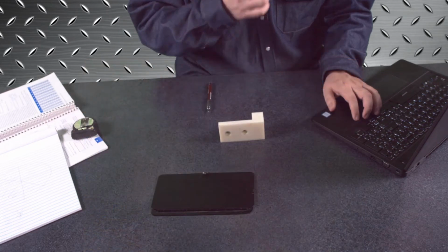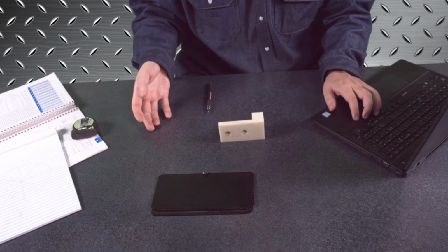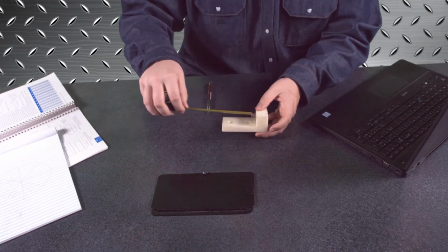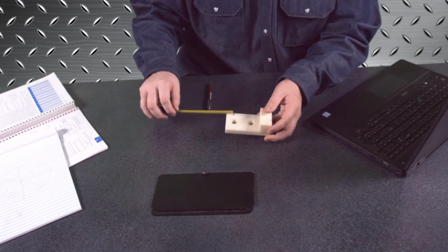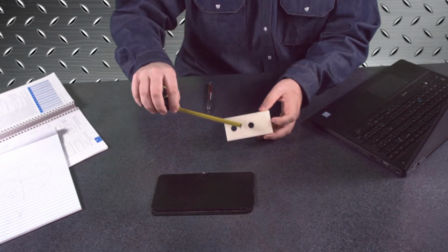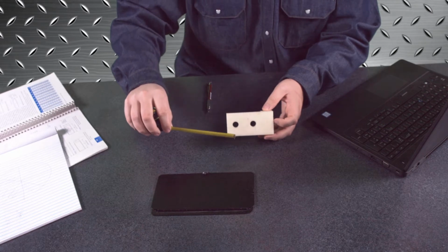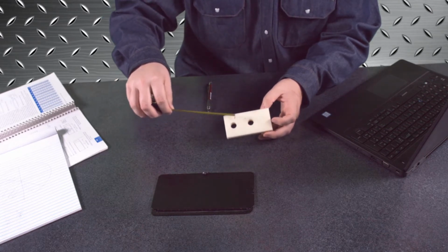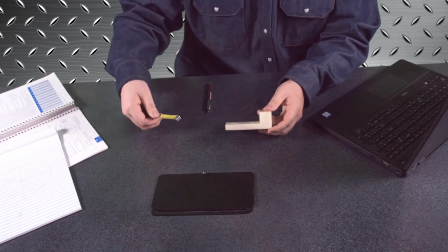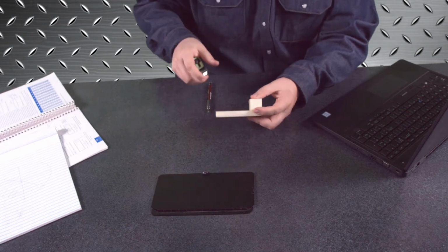So you have two types of dimensions. You have size and location. A size dimension is going to be how large the part is, and then a location dimension is going to let you know where certain features of that part are. So for here, if we put a center line in this hole and a center line in this hole, those dimensions would be location dimensions for where these holes should be, while a size or shape dimension would be for the size and shape of the part as a whole.